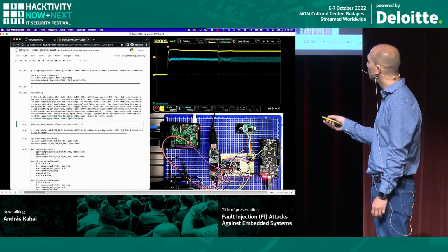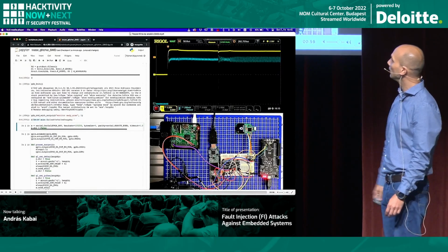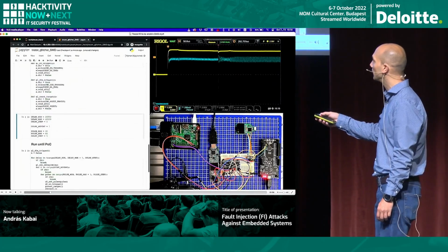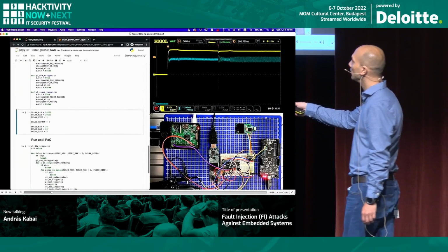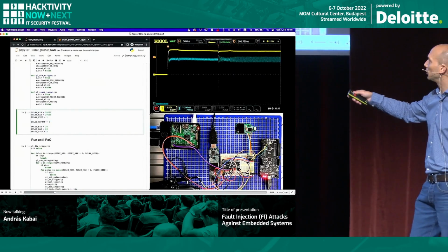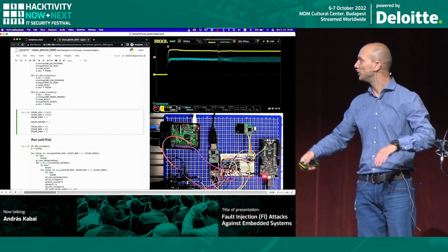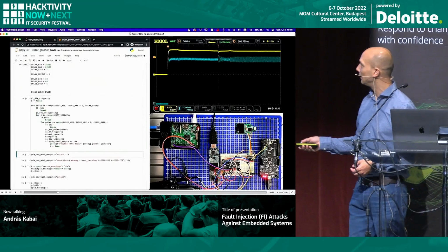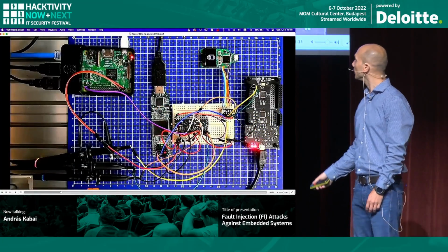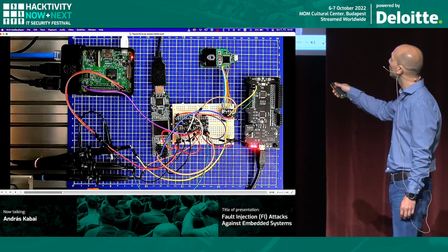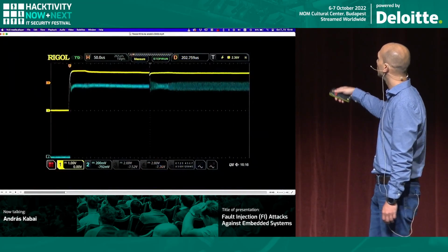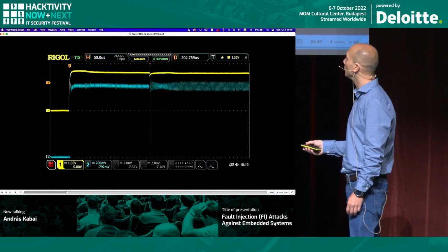And hopefully it will confirm soon that the debug access is not available. So we are going forward. These are really just supporting steps for the FPGA and configuration. And these are the settings that I use in the big loops that iterate over the various glitching settings with regard to the delay, the repeats, the pulse width changes, and so on. After executing the actual attack at this point, you can see that the scope started to update the waves and the Trezor started to reboot. So after every glitch attempt, the target is rebooted and the glitch setting is iterated to the next one, and the attack continues until we finally succeed.